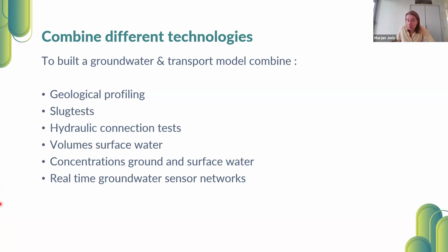Do you only trace contamination? How about remediation? We do measure contamination, but indeed we also follow up remediation, because a lot of remediation techniques have the objective to decrease risks and to decrease the spreading of the contamination. And then it's important you measure the flux instead of only concentration, because that will give you more information about the result and the effect of the remediation. So we do measure before and after remedial actions, for example.